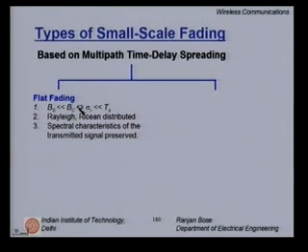In these scenarios, we typically find the received amplitude to be statistically distributed either as Rayleigh or Ricean. At the end of today's talk, we will introduce both the Rayleigh and the Ricean distributions. The spectral characteristic of the transmitted signal is preserved in the case of flat fading.